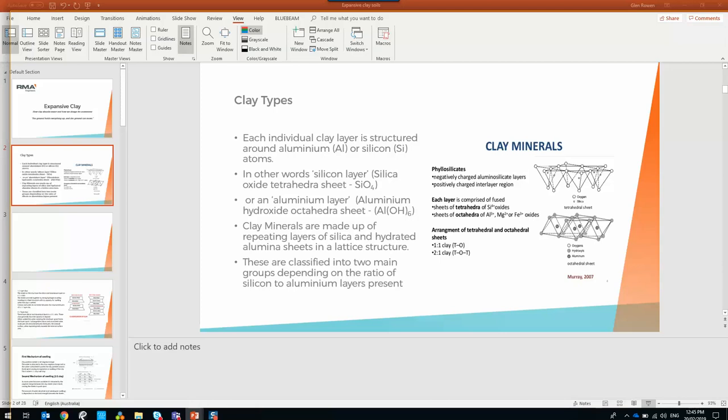So all that stuff from that 2.5 metres in, the soil's shrinking and swelling on the outside, and your system is basically fully suspended. It's really good when there's no plumbing or other trenches and everything that can lead water in.